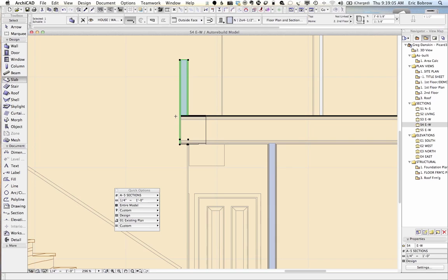So your references in terms of, this is a particular interior condition. So we need to drop this down. There's no interior wall underneath it. In terms of an exterior thing, we would usually take the exterior wall up to the top of the core, and then take the top wall down to above the core. Or potentially they can both meet at the zero of the story, the top of finished floor, if that's what you want.